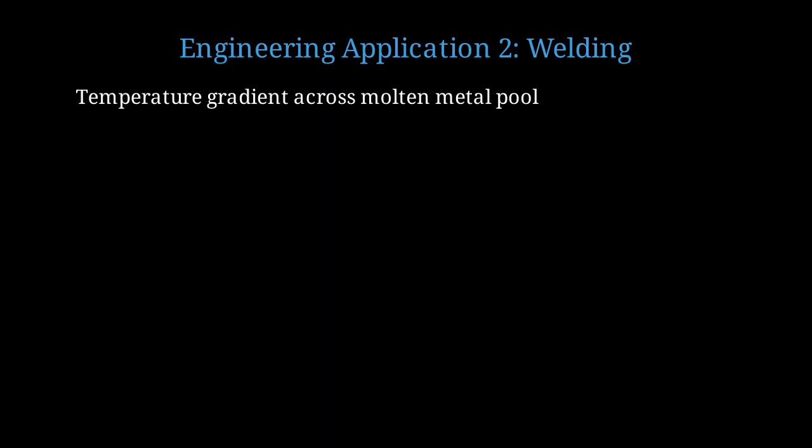Our second application is welding, particularly gas tungsten arc welding and laser welding, where Marangoni flows play a crucial role in weld pool dynamics. In welding, you have a molten metal pool with a very hot center where the arc or laser beam hits and cooler edges. This creates a large temperature gradient.